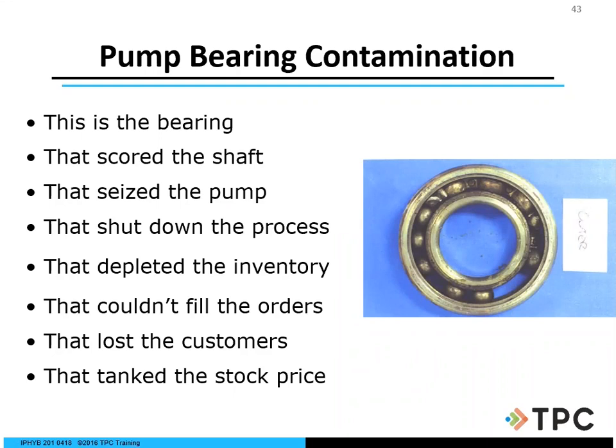We can have spalling effects, we can have overloading effects on the bearing. Take a look at your bearing. Bearings tell the story of why it failed. There may be electrical fluting with your motor, possibly because we're not properly grounded and bonded within our system. So we have electrical fluting within our bearings, which will cause marks, and then your bearing is not going to